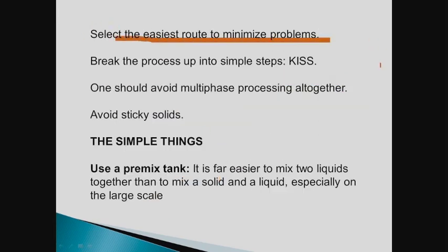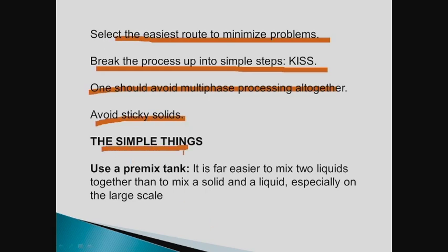Choose the easiest route. You really want to have the KISS principle. You want to break it up into simple steps. You want to avoid multi-phase processing altogether. That's probably unrealistic, since multi-phase may actually be your product. You want to avoid sticky solids. This is tough life here. You want to do the simple things.